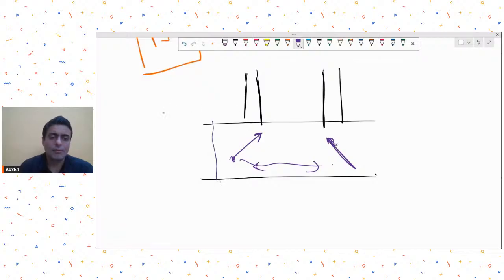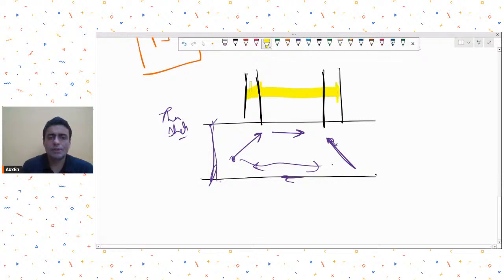Or maybe because of the thin shell assignment, you are missing out on the in-plane shear deformations which are exhibited in a thick shell assignment. So thin shell may have problems, especially when the depth is large and the support points are also quite close to each other.